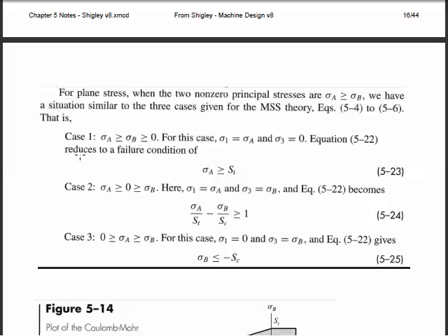is a plane stress case, if they are both positive, then this amounts to basically a maximum shear stress theory: sigma A greater than sigma tension. If they're both negative, this is almost maximum shear stress theory, except we're using the larger circle that comes from the compressive yield stress; sigma B exceeding negative compressive yield strength would cause failure. If we're straddling, sigma A is positive, sigma B is negative, we're straddling the 0 axis, then we use the governing equation that comes from the 2 tangent lines. So this is also a very simple theory.